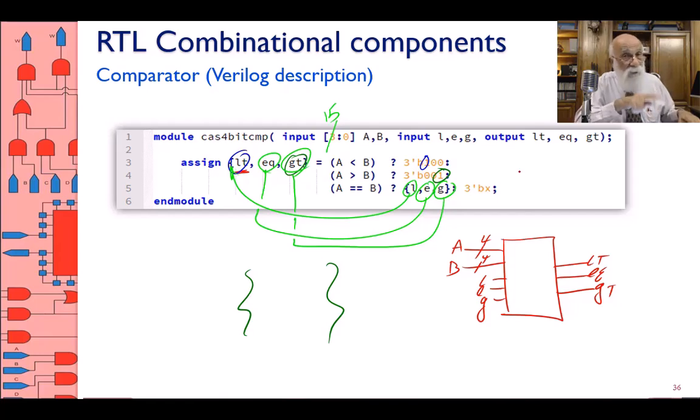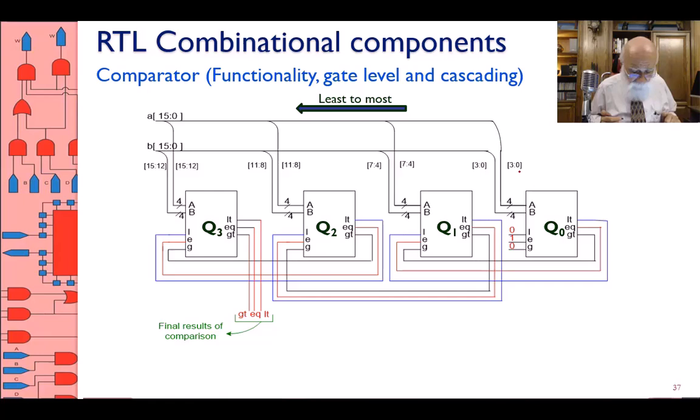But if you go and look in your bag of comparators, you only have 4-bit comparators, but then you want to build a larger comparator, this is how you do it. You take A[15:0], B[15:0]. Take the uppermost 4 bits, give it to the most significant comparator.